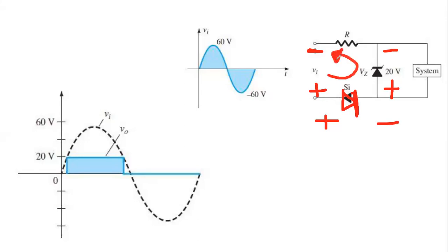My students, if this Zener diode is silicon based, not ideal, at that time there is no change in the forward bias, as I already told you. As it is forward bias, we can replace it with 0.7 volt if it is silicon based. So at that time the output voltage will be -0.7 volt if we consider something like that, because you see that the direction minus is upper and plus is low. But if it is the ideal diode, when it is forward bias, there will be no voltage drop. At that time the system has zero voltage output, and all the voltage will be dropped in the resistance.